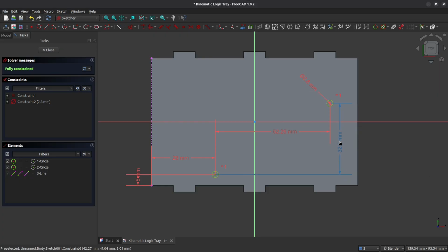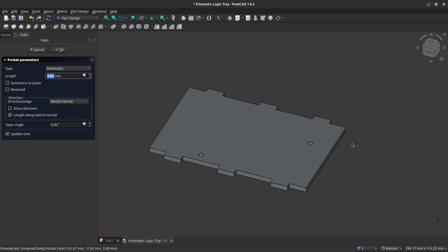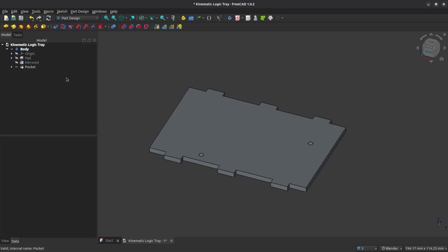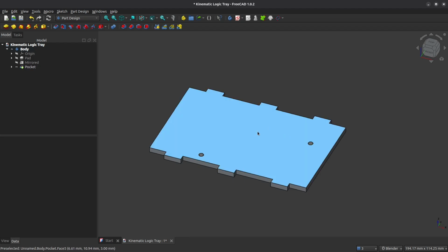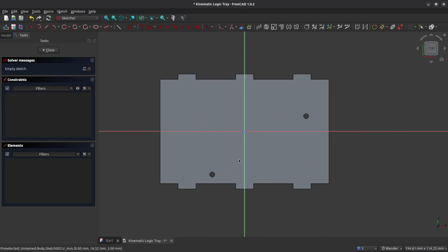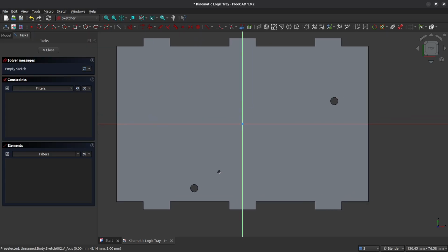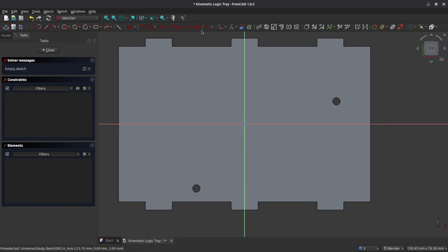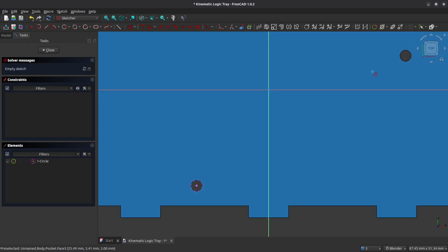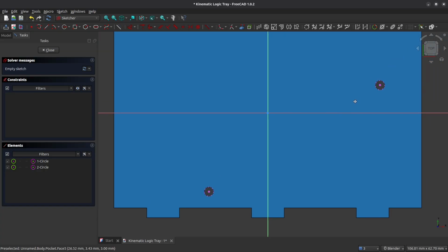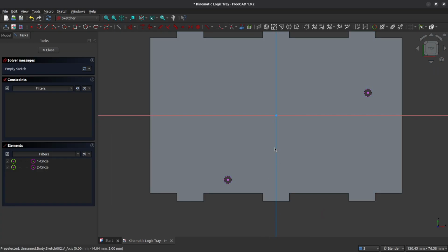All right, so we've got the two screw holes that will be used for securing the Arduino created, and now we're going to pocket these. Our next step is to create standoff bosses. The through-hole components on the Arduino Uno have a tendency of creating torsional stress on the Arduino Uno when you are trying to screw it down. So these standoff bosses will ensure that the board doesn't twist when we are doing the screws up. It gives it a nice flat datum plane to work with.